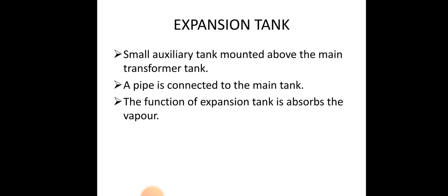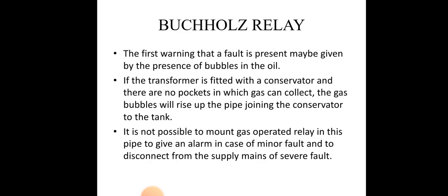A small pipe connection between the gas space in the expansion tank and the cover of the transformer tank permits the gas above the level to pass into the expansion tank. So the transformer tank will always be completely filled with oil. And next one, Buchholz relay.